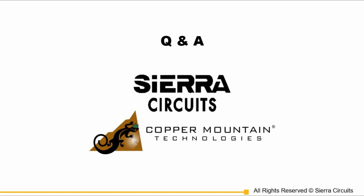I'd have to look, but I actually had to zero in on it. Let me make one more comment: the inverse transform that we're doing is not actually an inverse Fourier transform. It's an inverse chirp Z transform. The reason is that the inverse chirp Z transform allows you to zoom in on a time domain response cleanly.